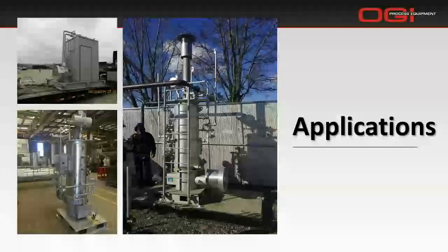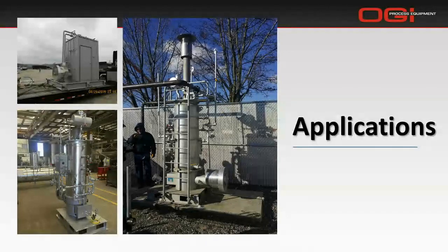And a couple additional benefits to this type of a heater would be higher efficiencies, close to 85% in some cases based on design. And if you were to compare that to a horizontal water bath heater, the efficiencies there could be anywhere between 60 to low 70s. And we'll talk about what kind of design principles you can use to be able to get those good thermal combustion efficiencies.